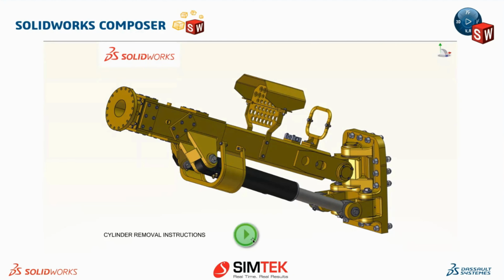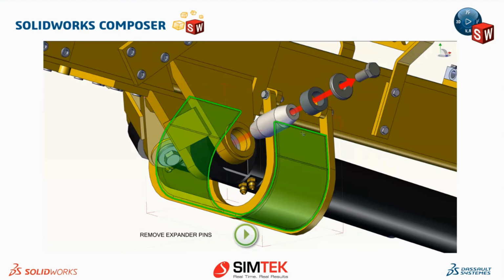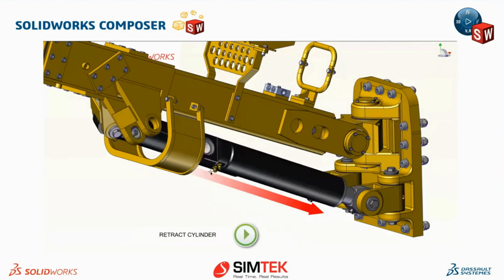See now, by pressing this next button, what is this? Cylinder removal instruction. By pressing this next button, see what's happening. How to remove this extended pin from where. It's also having the text or description like remove expander pins. Then what is next? You should retract the cylinder to this position like mentioned in the arrow.